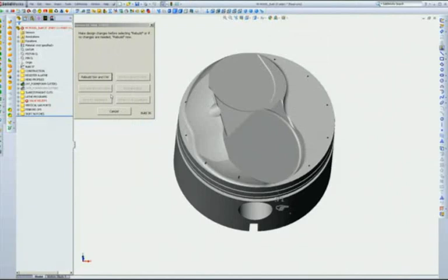There we go. I just wanted to point out these very small holes at the very top of the piston. Those are like a 47 thousandths hole, very tiny drill bit goes in there. As you can see, some of those holes are on drastic angles and curves. That's not something you would normally want to just take a drill and try and drill. It'll snap that little drill in a second.